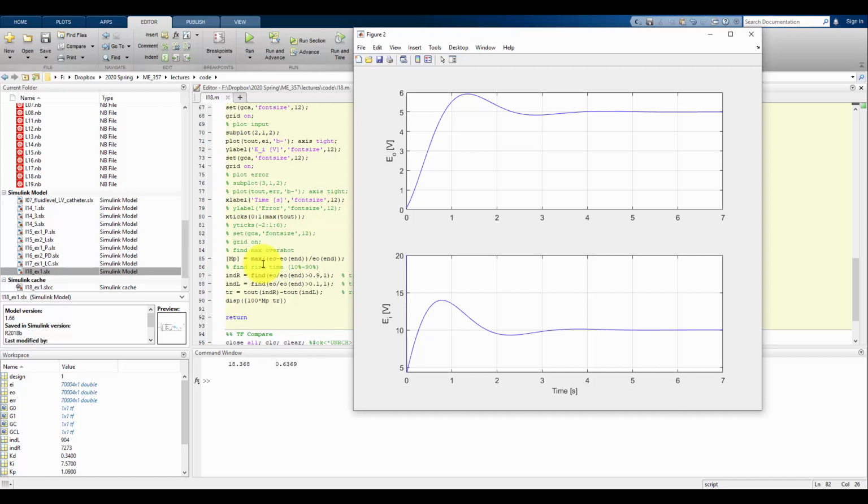And if we look at the input on the bottom, it does immediately spike up to that maximum of 20 and then comes down pretty quickly. And then we see it follows through and doesn't even go above about 14 volts again for our input effort. But that limiter, we're going to see in a second, does have a big effect on how this can perform, that we can only provide that instantaneous 20 volts when we put this limiter on.